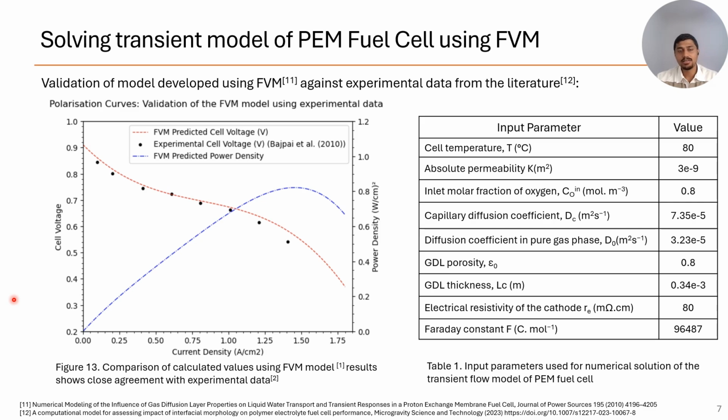All right, just like any numerical model, its validation is important to ensure reliability under real world conditions. One of the common methods to validate fuel cell performance is the polarization curve, which shows the relationship between cell voltage and current density. Basically, it means how much voltage a fuel cell can deliver for the required current load. Okay, let's look at the results.